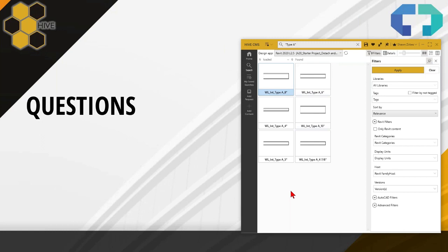What I would recommend instead is uploading your training videos to something like YouTube or Vimeo, and then placing a link to the video in Hive. And the reason I recommend that is because if you upload the video to Hive, before an end user, one of your designers, can use it, it has to cache the video, re-download it to their workstation, and then play it from their workstation, which takes longer.